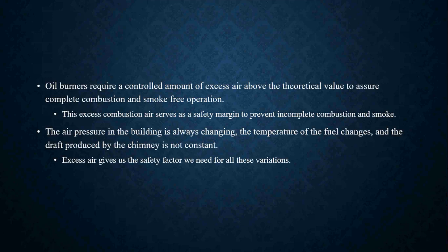That's why when an oil burner is firing, you don't see the oil mechanic come every single day back to the home and make adjustments on the air shutter to help keep that unit running at a percentage of efficiency. It's because of the excess air.